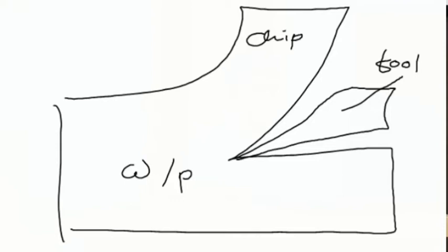So during the cutting, there are some chances that some fragments from the chips get welded over here on the rake surface of the tool, and these welds get broken after some time due to the relative motion between your workpiece and tool.